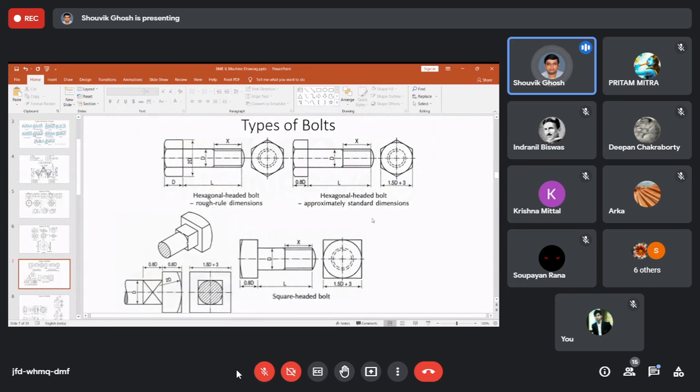So nuts are here, now coming to bolts. A bolt is basically the partner of a nut, and the set of nut and bolt is used to fasten two portions of a machine, or to fasten a machine to another part or similar things. In a bolt you also have the same calculation of d and 2d and x. All these values are there. This x is the length of the thread.